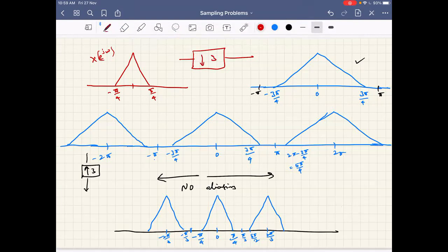So now with this, what we do? We apply a filter. What is the filter frequencies? Minus pi by 3, 2 pi by 3. And hence what will be the output now? Minus pi by 4 to pi by 4 replica will come. Only that one. Minus pi by 4 to pi by 4 will come out.